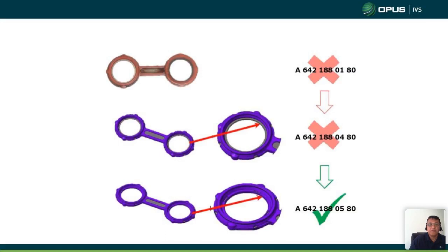So that's the part number of the latest, and see the difference: I think this one is all made of plastic, and that one has steel or metal surrounding at the end. So it could be superseded again. So double check with your parts department what will be the latest part needed when you're replacing the seal, or you're replacing the oil cooler for the engine. So these are the 3 part numbers.